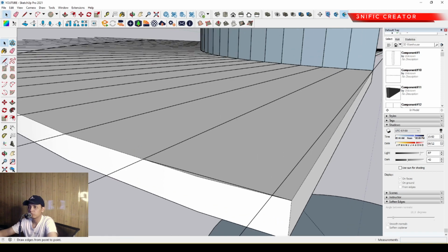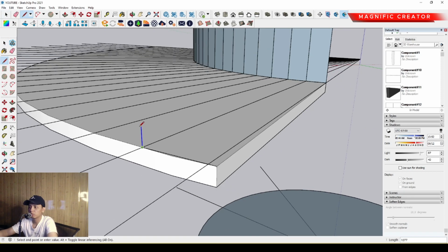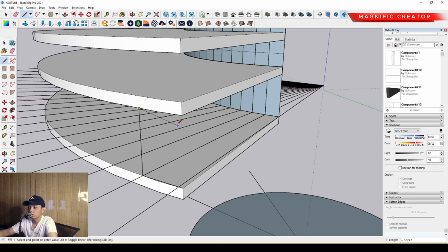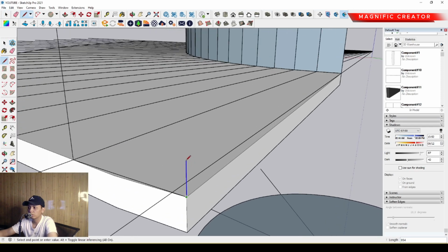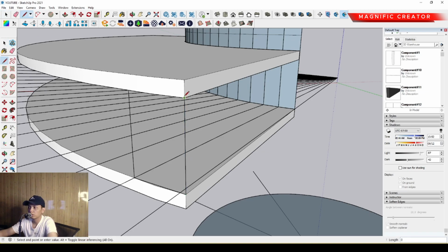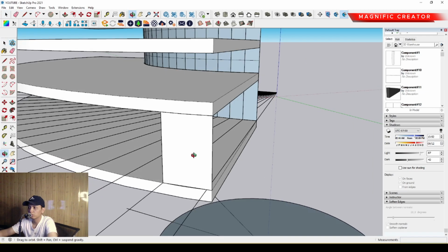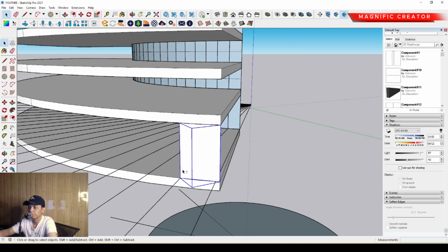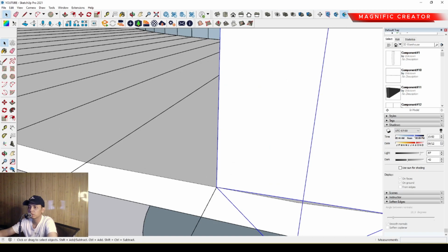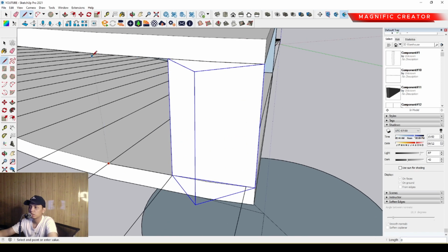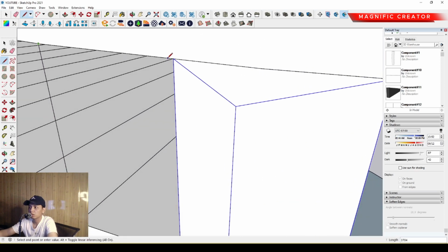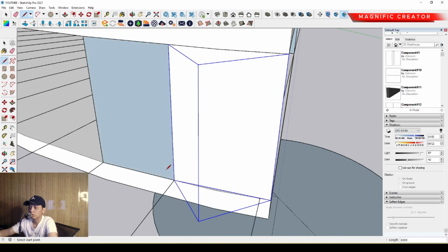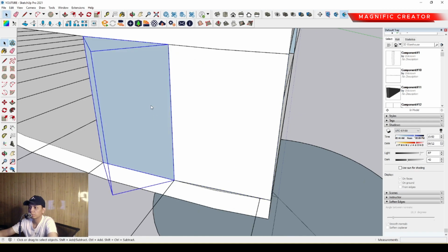So then we have to use the line tool, and then we can push it up. And then we can use a vertical line also over there. Then we can place it on this, so it will be the first type of glass panel, and make a group, make it a component and create it. And the second type of glass panel on the back wall of this high-rise building is smaller than the first type anyway. This is the second type. Okay, and then we can make it a component and create it.